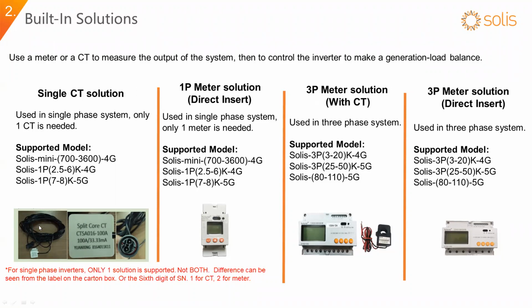So you can see our CT and cable and also the connector are already pre-made. So when you get the package, you just need to plug the connector into the inverter, and then the connection is done. All you need to do is change the settings on the inverter LCD. It's very easy and plug and play.